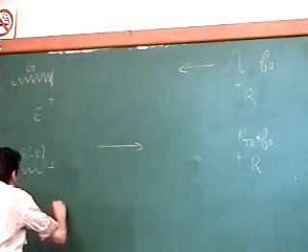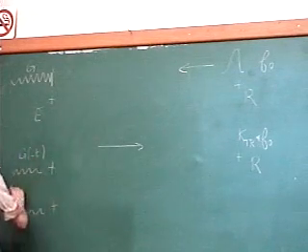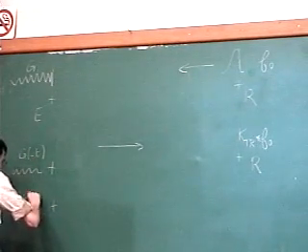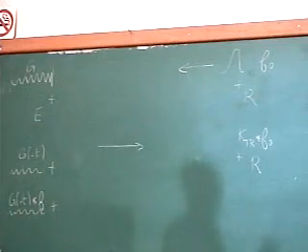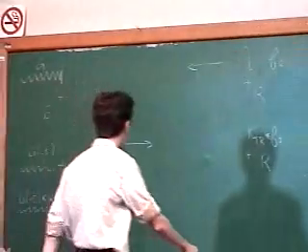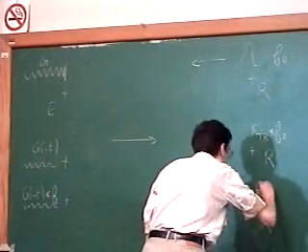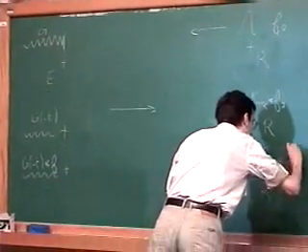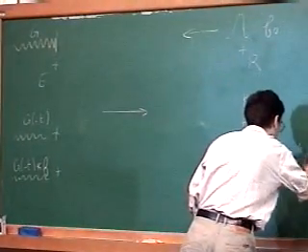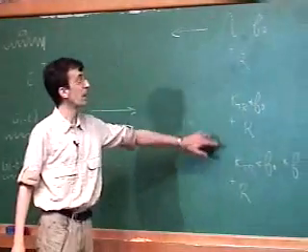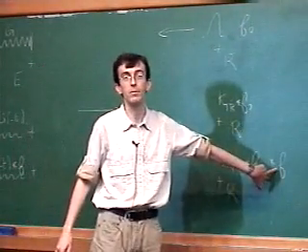And third step, your receiver is sending not G(-t), but G(-t) convolved with F, the information. And what R will receive is KTR convolved with F naught, and the medium is linear, the wave equations are linear, so convolved with F. So by a straightforward deconvolution, R can extract F.